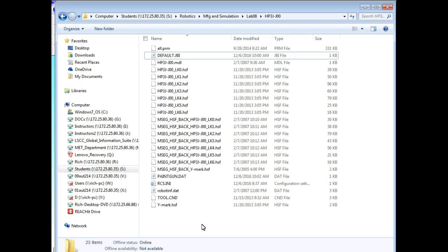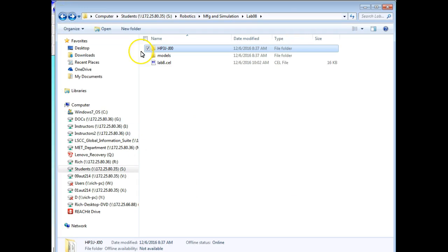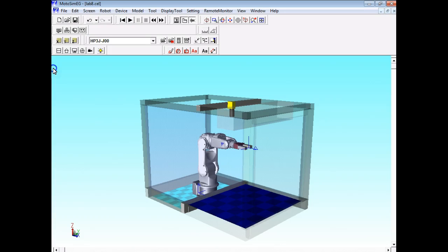Into your robot folder. And then you'll have a copy of that job. Then when you go and look in your jobs folder, when it's running, that job will pop up. You'll select that job. You'll come up and you'll run it. Right? You understand. See what it does. Then what are you going to do? You're going to modify it. Then you're going to check it with collision detection to make sure it doesn't what? Collide.